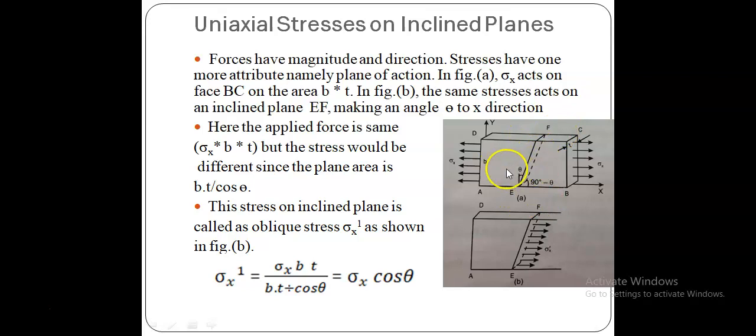Here also the force is the same, because only then will the system be in equilibrium. That force can be calculated as sigma x into b into t, and the same force is acting on this plane. The forces are equal, but the stress differs.